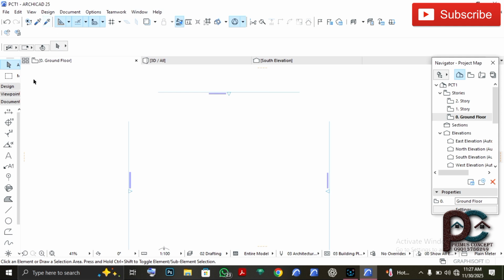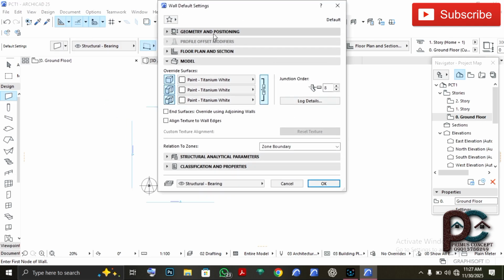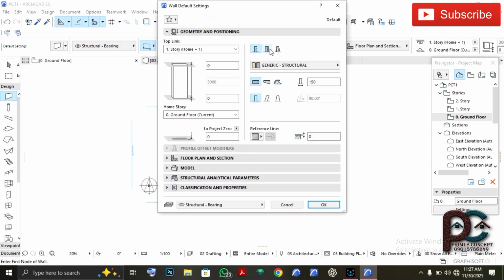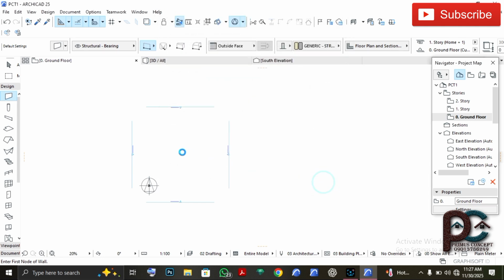So let's start with using our walls. We go to our design, use our walls, and then we go to the settings on the walls, and click on this. Once you click on this, you set the dimension of the wall. Because it is a ground floor, I'll make it 150 for the thickness of my wall. When I come to this place, I'll use this, and then we're okay with that.